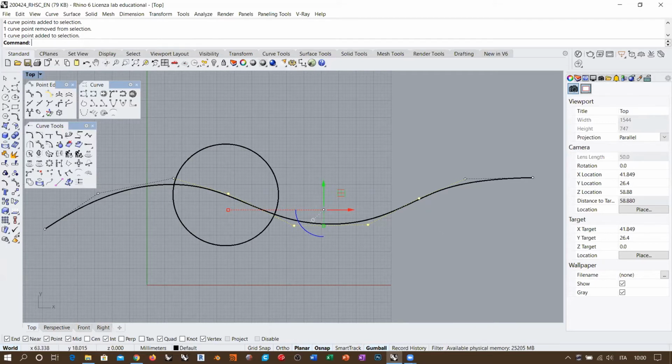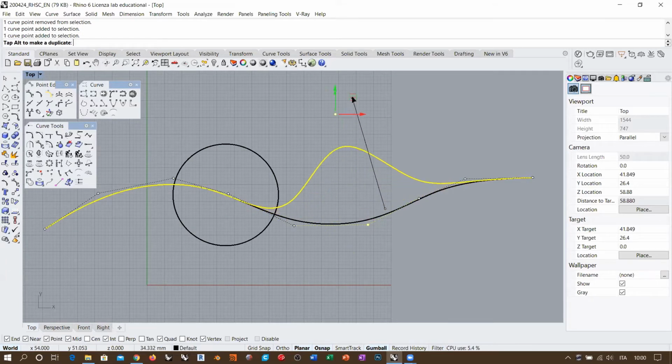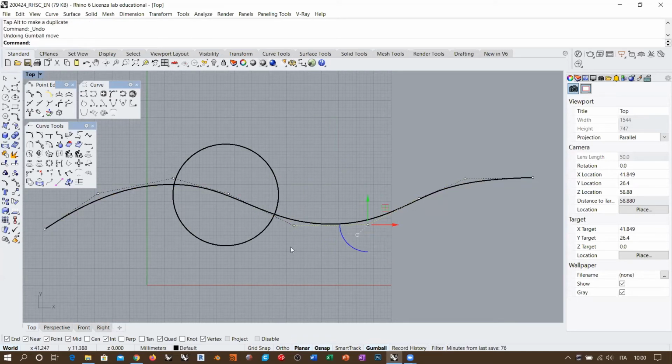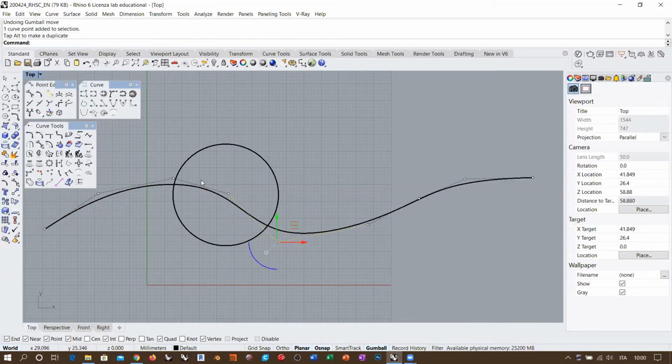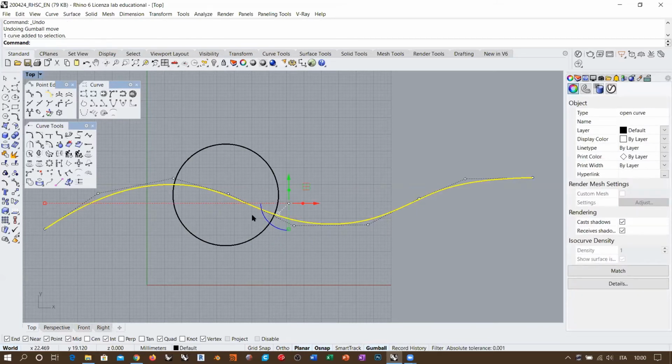That's why local deformation is a problem, because if I move this point, I am changing the shape of a whole set of curve, which is a huge amount of curve. And also if I take this one, I am basically affecting more or less the same area plus an additional span to the left. So how can we determine local deformability?